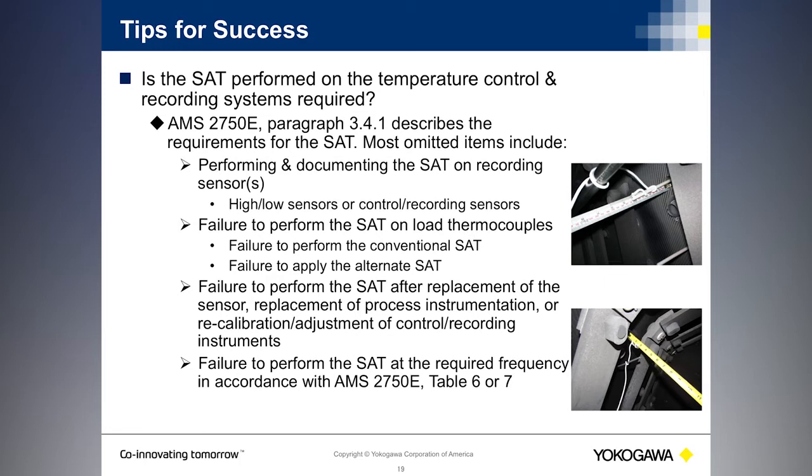Failure to perform the SAT after replacement of sensors, replacement of process instrumentation, or recalibration adjustment of control or recording instruments. Not performing the SAT at the required frequency in accordance with AMS 2750, Table 6 or 7.